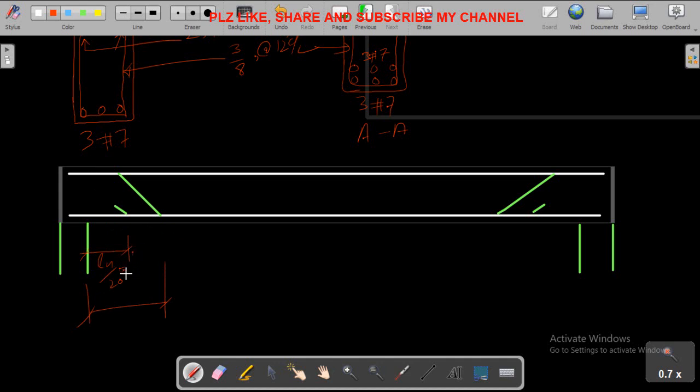This bar should be bent up at a distance of Ln by 7, so 25 times 12 divided by 7, it will give me 3 feet 6 inches. So this is bent up to the top, and again this is 1 number 7 bar, and this bar should be discontinued at a distance of Ln by 20, which is 15 inches, right?